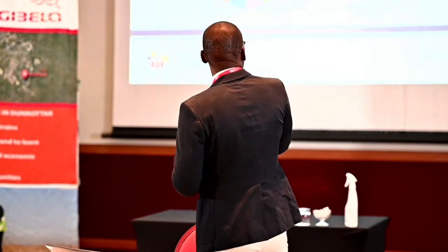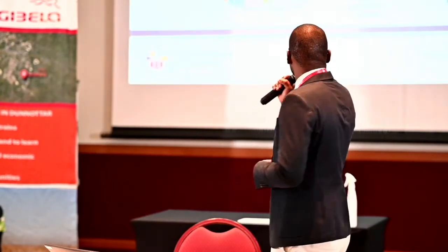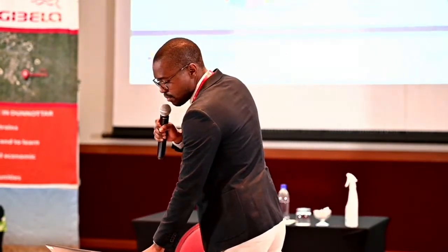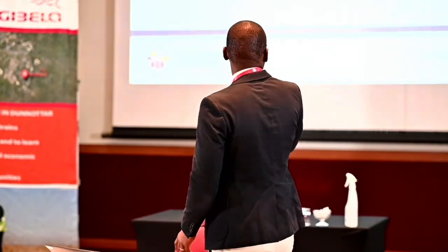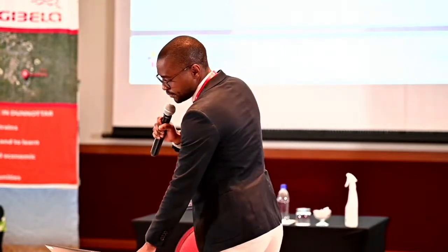There are also root causes that I was able to evaluate. Cable theft came out tops, which is also on the feeder performance. On the Mokwasi feeder, as you can see, most of those faults occurring are from cable faults.